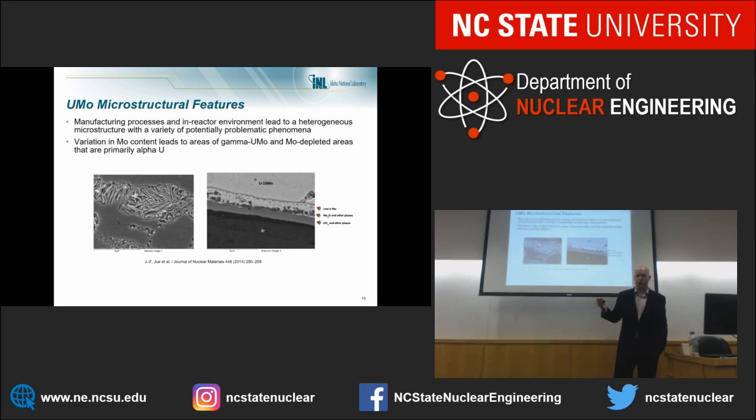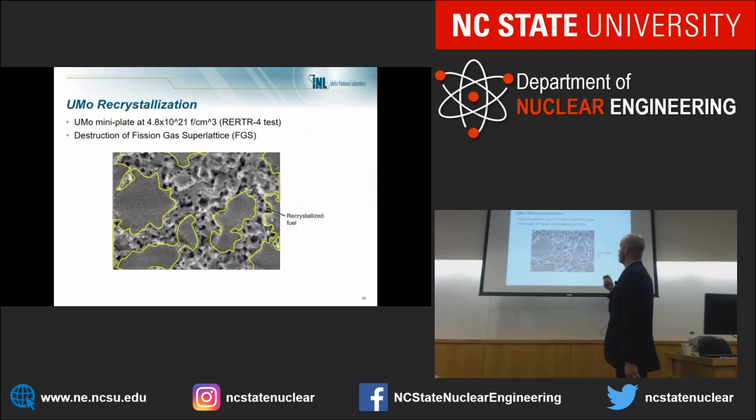And this is all important because one of the failure criteria for these fuels is debonding of the clad. So if this layer fails effectively and it becomes debonded, we're going to have a buildup of fission gas in this pocket that's formed, which causes a pillow on the outside of the fuel, which can lead to coolant channel blockage and essentially fuel failure. So this is a variety of the things that we're looking at and studying in these fuels.